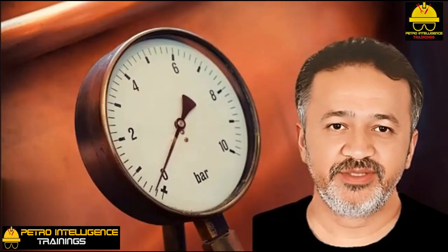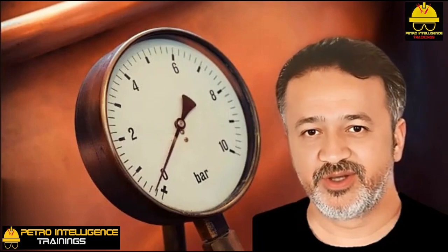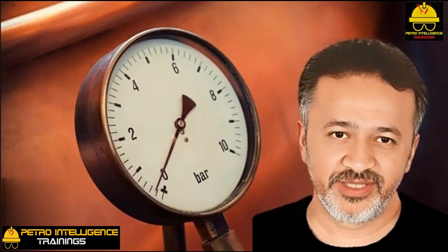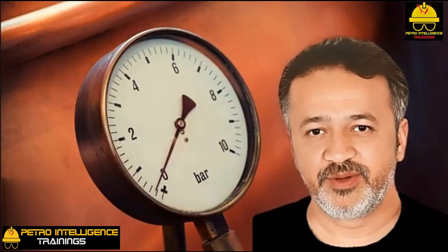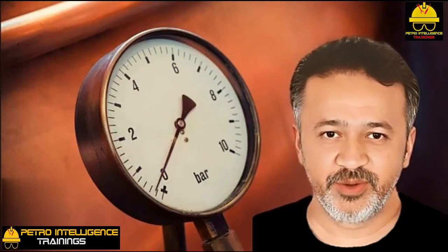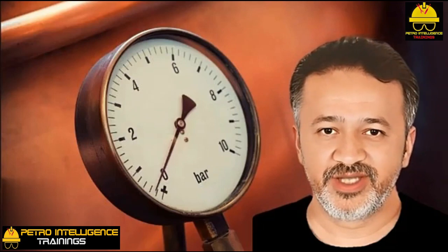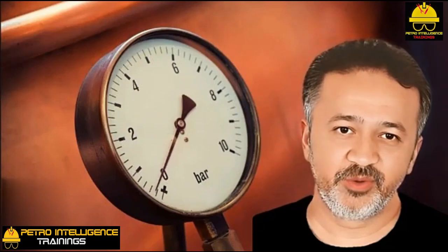Short thermowells. For a thermocouple to read correctly, it should be fully inserted in a thermowell, and the thermowell itself should extend several inches into the process liquid. If the process stream is a vapor, which has poorer heat transfer properties than do liquids, the thermowell, especially if the external insulation is poor, should extend more than 6 inches into the process flow.